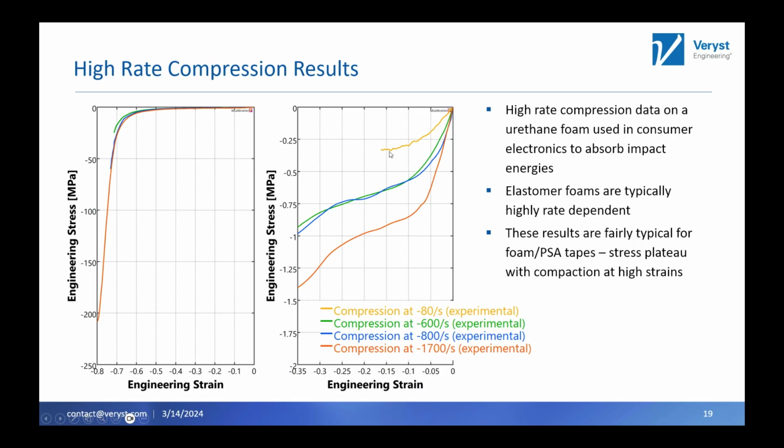But this plateau level is extremely strain rate sensitive, even at something I would still already consider to be a high strain rate. So it is really important to measure the behavior of these materials at multiple high strain rates.